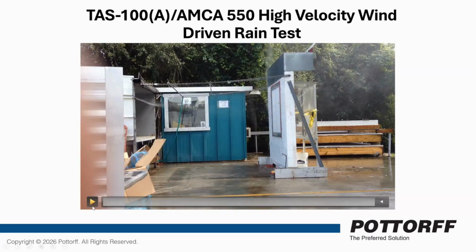This one isn't as exciting, but that's the 550, the high velocity wind-driven rain test, again, the water test for a hurricane. Here you can see water spraying. You're going to have the louver in this wall here, with some type of collection chamber. It's open in the back so air can actually flow out. Remember that from the pressure drop: if you have less pressure, air can move through it, which is good for this test.